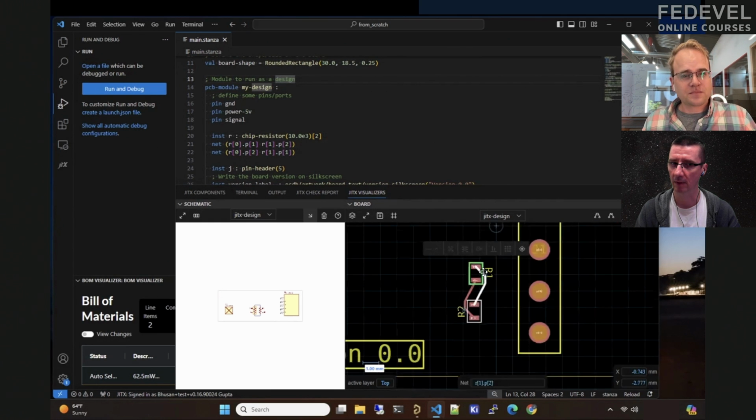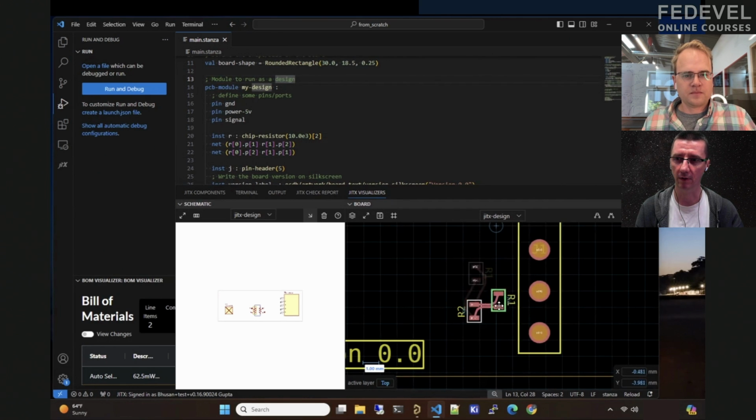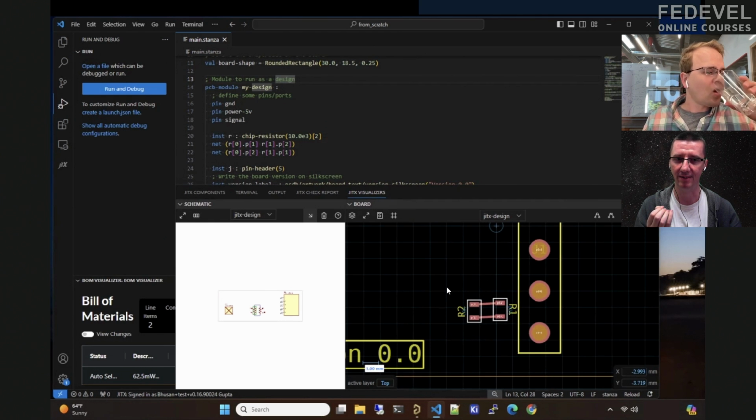unless you actively try to break them. This can sometimes be tricky because, for example, when I'm doing layout, very often I actually break many rules just to be able to connect everything or see where the space is, and then I will reroute or fix it later. When I was trying AutoRouter, one of the biggest problems with this setup was that you set up all the rules, but you end up with a design which was not able to route at the rules you specified. So how do you handle this?